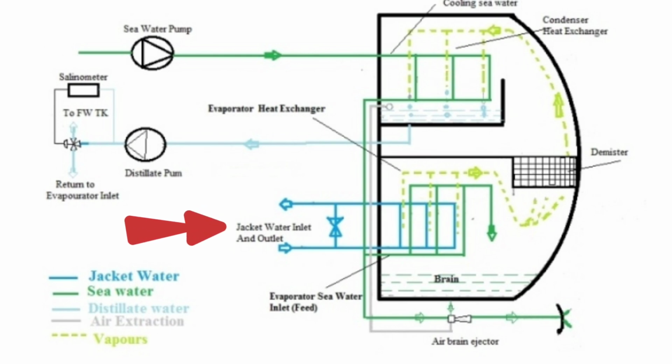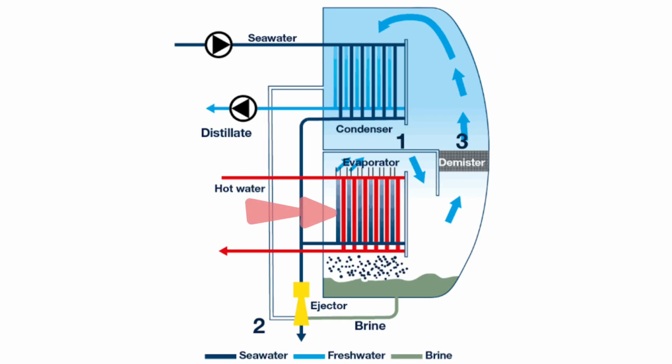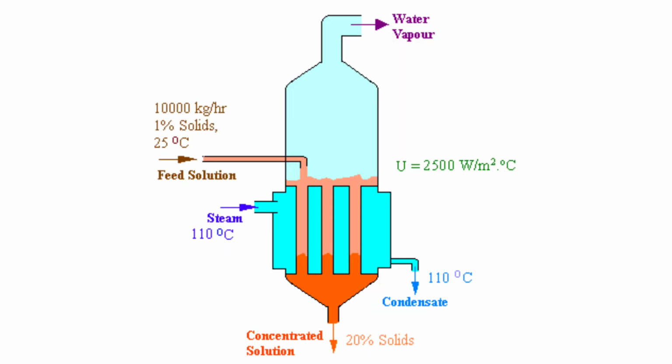The source of heat for the freshwater generator could be waste heat rejected by main engine jacket cooling water. Hence, using energy from a heating coil and by reducing pressure in evaporator shell, boiling can take place at about 40 to 60 degrees Celsius. This type of single effect plant is designed to give better economy than absolute boiling evaporators.